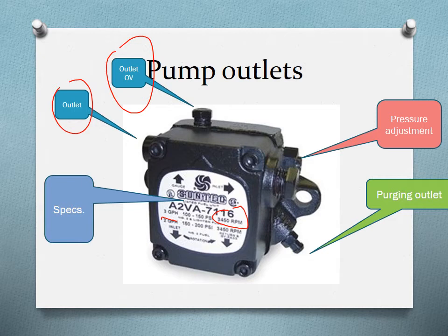And again, if we keep the pressure between 100 and 150 psi, that is the case. If the pressure goes between 150 to 200 psi at the same RPM, you can have 2 gallons per hour. So if you notice, the amount of flow that's coming is decreased, even though we are at the same RPM and have higher pressure.